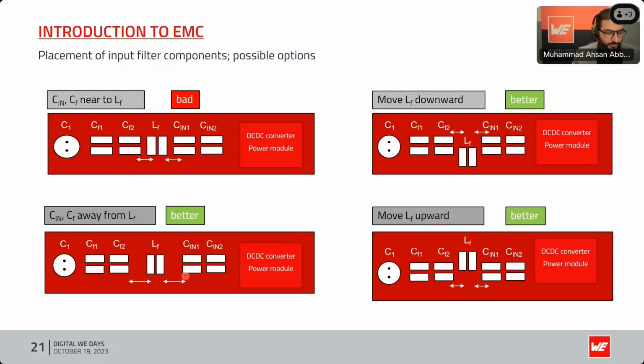But if you have no space constraints, if you have enough space, if you can move your caps away from the inductor, you can do it as well. And it is then the question of the cost, if you want to use a shielded or unshielded one. But we can clearly see that the magnetic couplings around the components of unshielded is much higher than the shielded inductor.